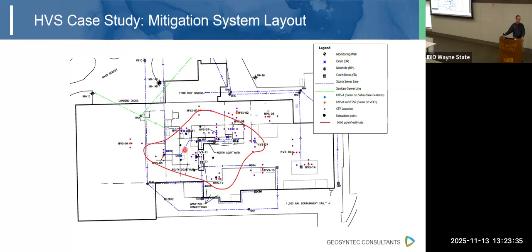Yeah. I think what Wisconsin does, and I'm more in favor of this approach, is having different screening levels for the lateral, between the house and the main, than for what's in the main itself. For the main, I've seen 0.1 or 0.03 attenuation factors, but then an attenuation factor of 1, so no attenuation, from what's in the lateral or service line to indoor air. Okay.